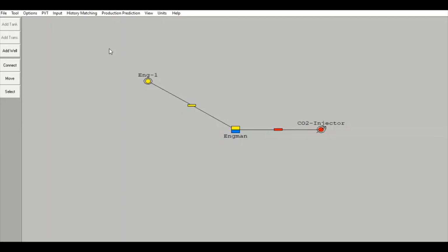I can store my CO2 continuously until the final reservoir pressure is relatively close to 3,150, which is the frac pressure, but still well below that. Let's say I will make the maximum final reservoir pressure 2,700. Okay, 2,700.